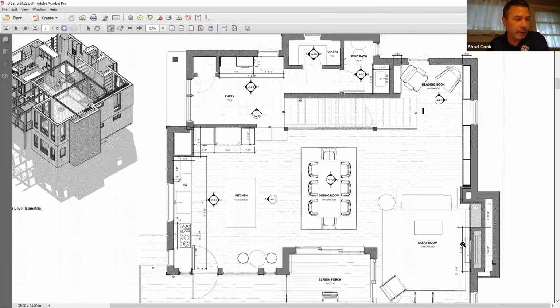Yep. Probably could even get away with 8 by 16 if we needed to. But then turning that, if you're coming up through a chase and then turning direction going lengthwise, you may be better off getting to more of a square duct. Yep, that's true. But if we come up in this area, then we've got to elbow up at the ceiling of the first floor.